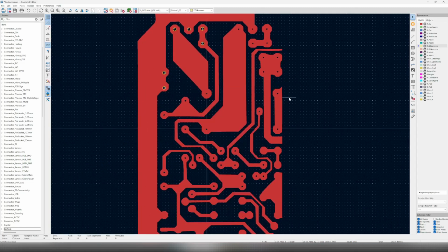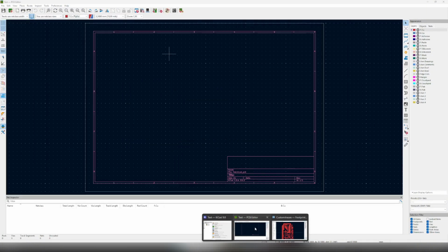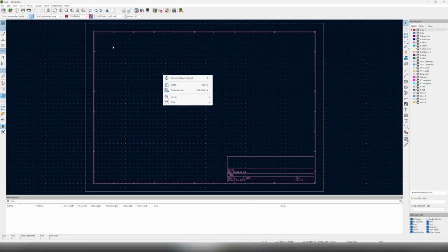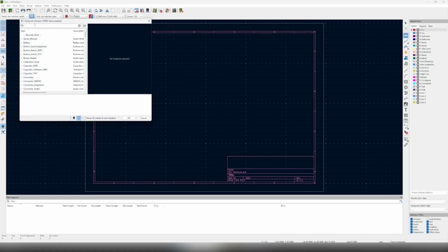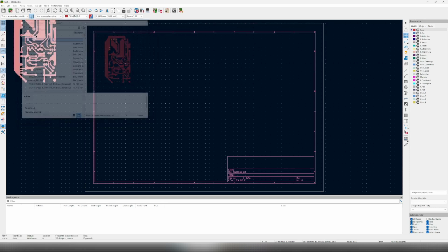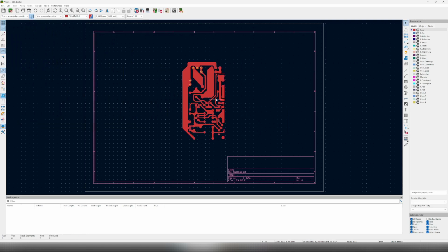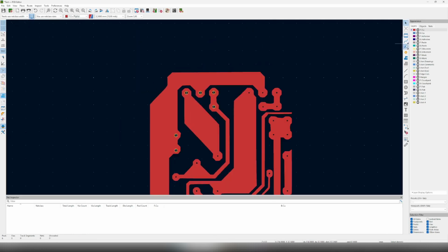And voila, let's say it's now finished. So I save this, the custom footprints. Let's go back to the PCB. In here we can place footprints now, which we're gonna do on our PCB. Voila. And here you can start placing other components if you want to, or creating vias.